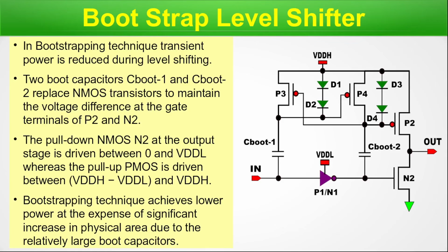The bootstrapping technique achieves lower power at the expense of a significant increase in physical area due to the relatively large boot capacitors. We're done talking about the bootstrap level shifter in this slide with a neat diagram. So let's move on to the next slide.